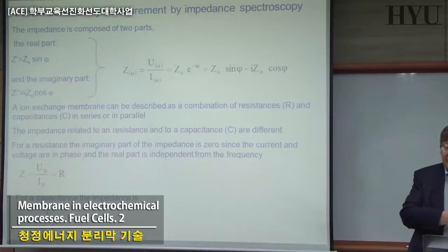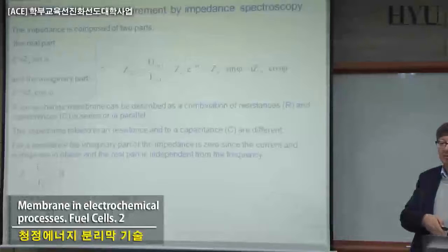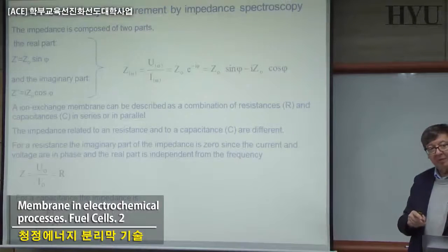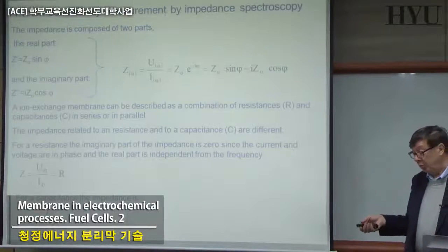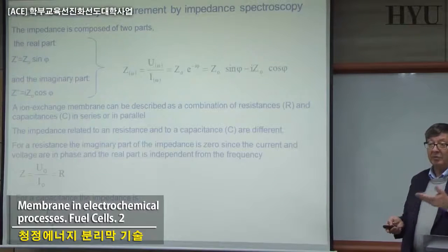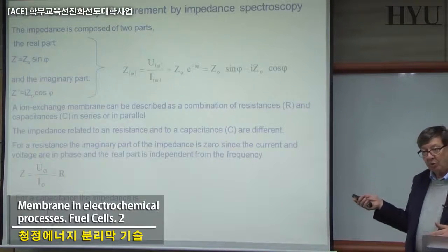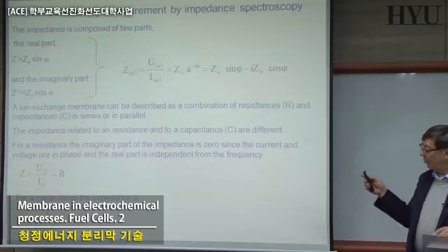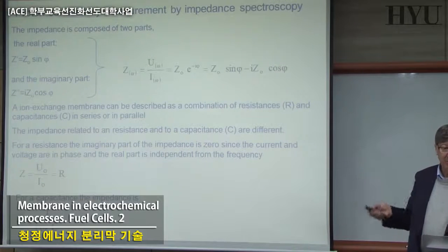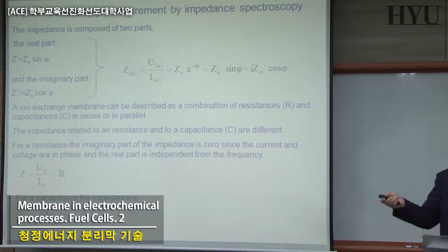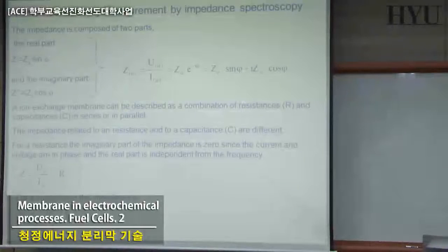So if you have a solution in which magnesium is present, you have to be careful, because the membrane stops working because of the magnesium, not for other reasons, which is also giving you an answer. You can remove magnesium and the system will work. But there is no way to understand this if you are not using a methodology of this kind. We will discuss this when talking about reverse electrodialysis, where we have this slide showing it.